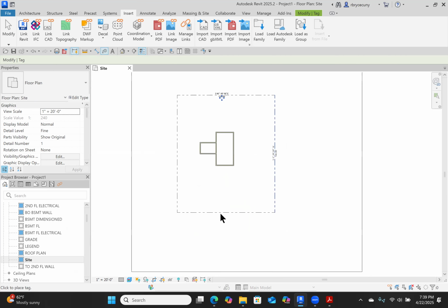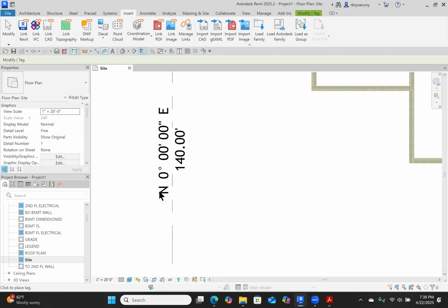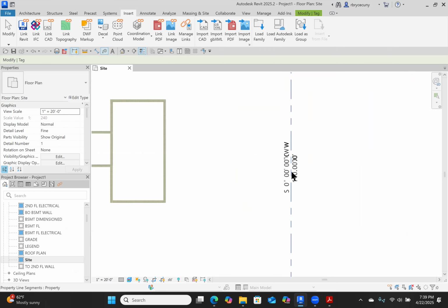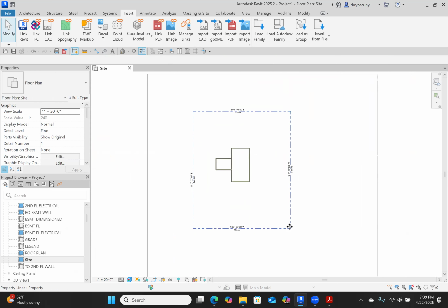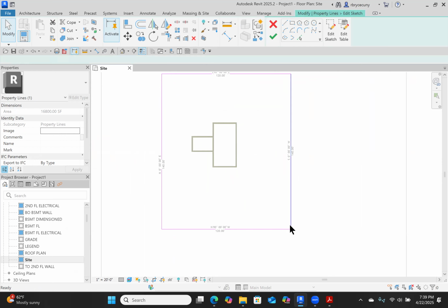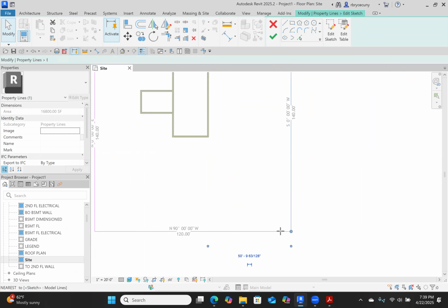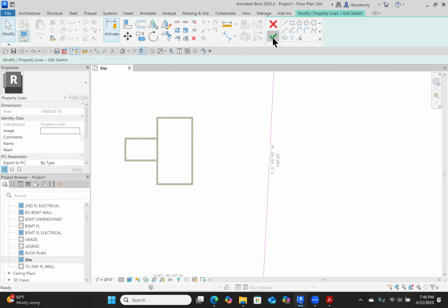I happen to probably have drawn perpendicular lines, but generally, it's possible that those lines would have an angle to them, but apparently I was very simple about it. Let's see what happens if we grab one of these. I'm going to edit the sketch, and I just want to drag this one over a little bit so that there's an angle to it. Then we'll trim extend. I still call it fillet from the old AutoCAD days. And we'll say okay to that.